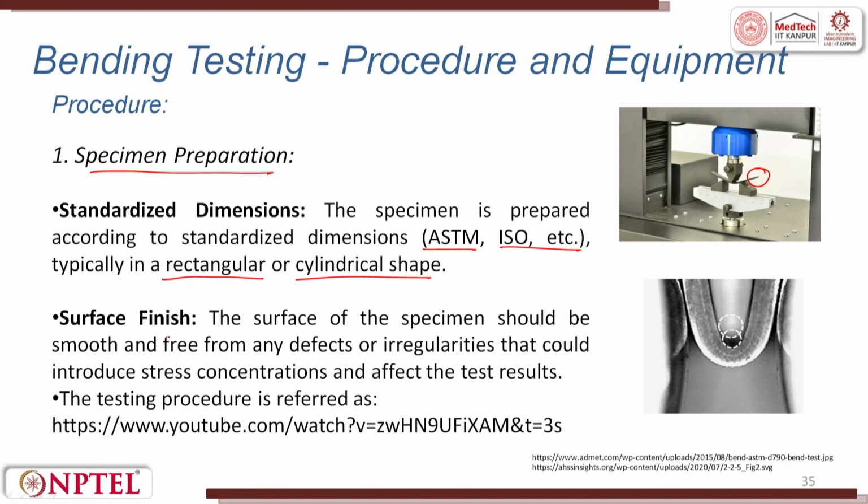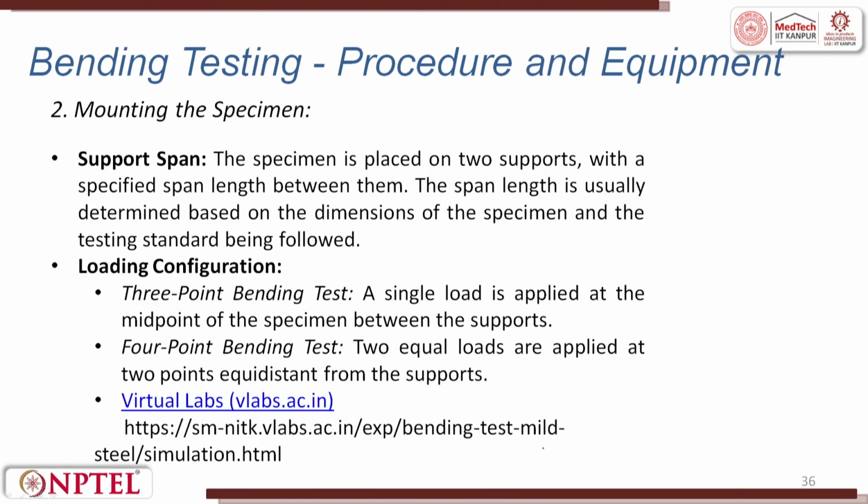Then we have surface finish. Surface finish of the specimen should be smooth and free from any defects or irregularities, so that it does not introduce any stress concentrations and does not affect the test results. There is a YouTube video, I will show you the video. Let me go through the procedure first.